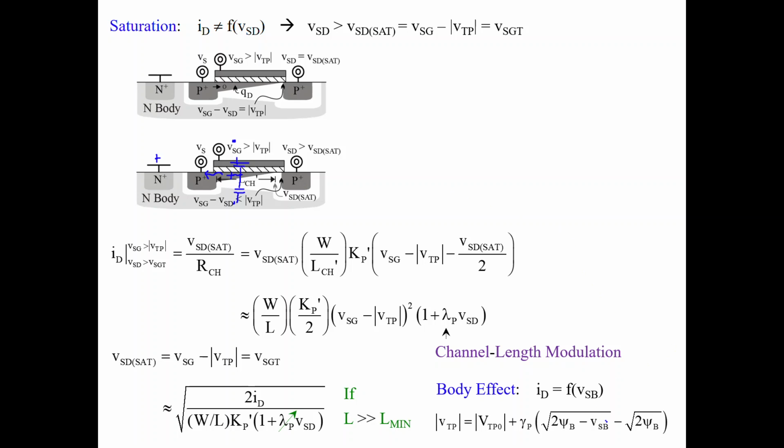So if we increase the body voltage here, we make this more negative. So this whole term here becomes positive. So this term is greater than this one, so that difference is positive, multiplied by just a constant. We add voltage to the effective threshold. This is just a modeling expression. So we're modeling the effect of the bottom gate through the threshold voltage.